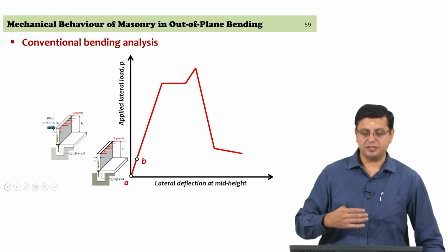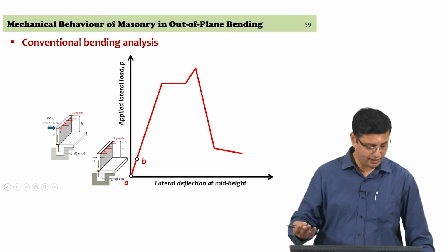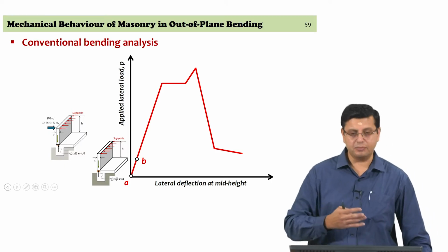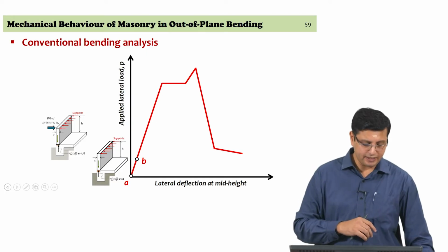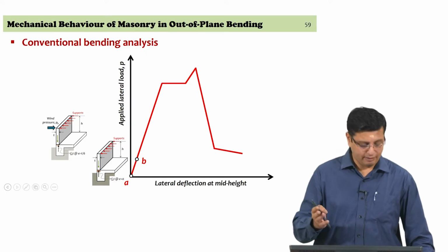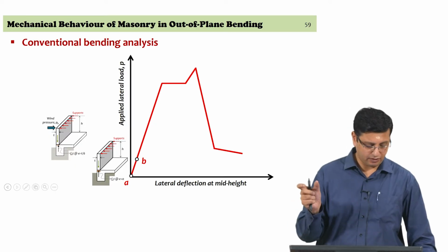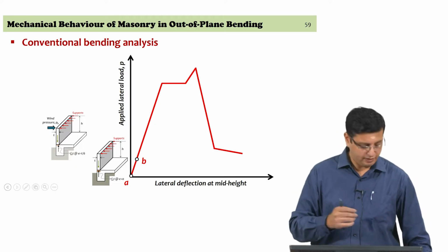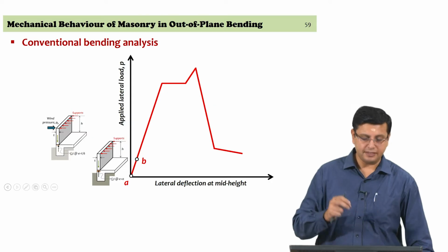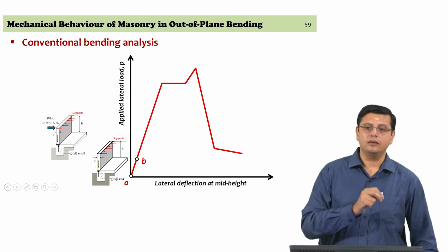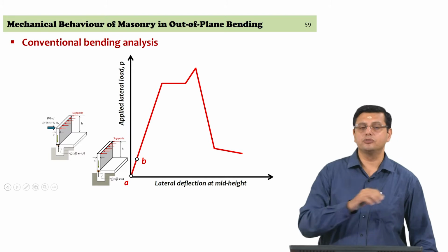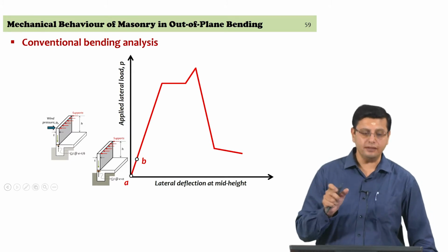As long as the wind pressure or the lateral force is low, they get nullified by the compressive stresses, but then you take it to the limiting case where there is still no tensile stress, the entire cross section is in compression, but that gives you a limiting case as to what will be the wind pressure corresponding to the entire cross section still being in compression.